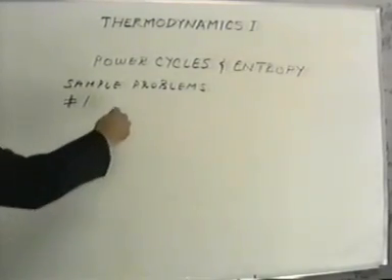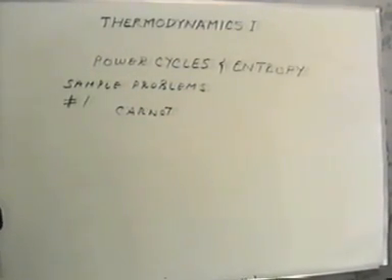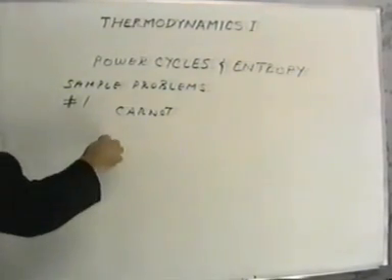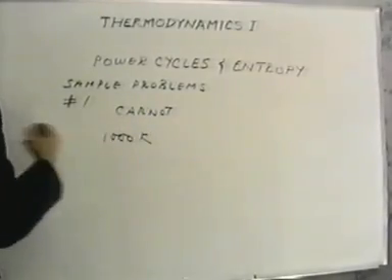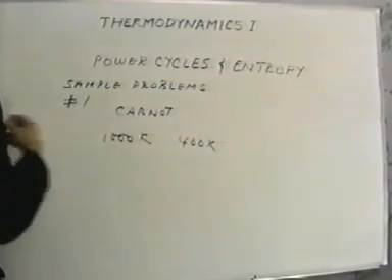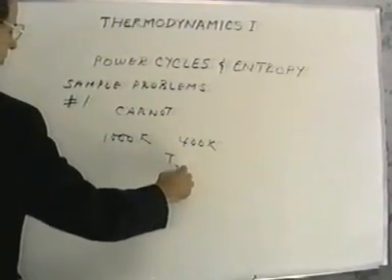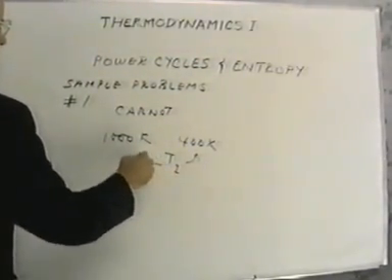we have two Carnot engines, that's the key word, two Carnot engines in series such that the heat rejected from one is the heat input to the other. The heat transfer from the high temperature reservoir is 500 kilojoules. If the overall temperature limits are 1000 K and 400 K, and both engines produce equal work, find the intermediate temperature between the two engines. There's some temperature in between these two extremes.